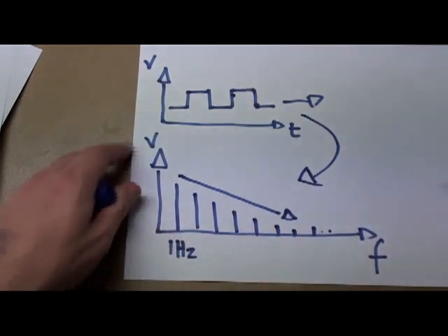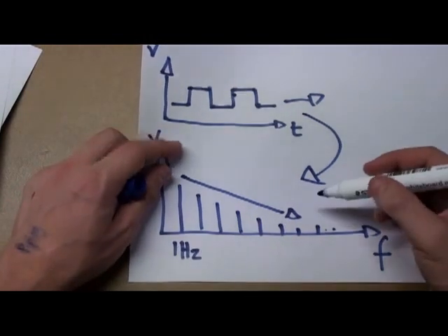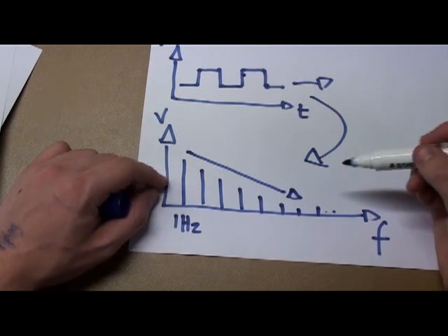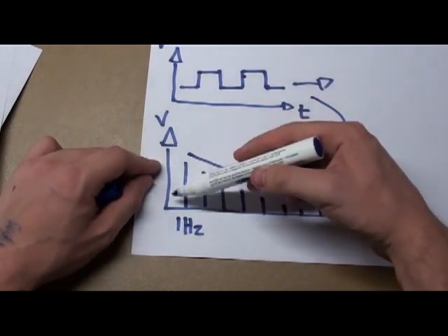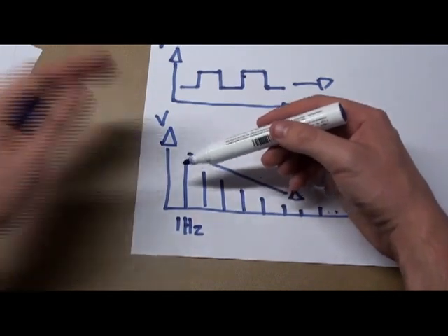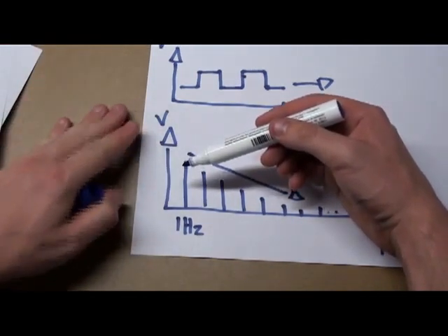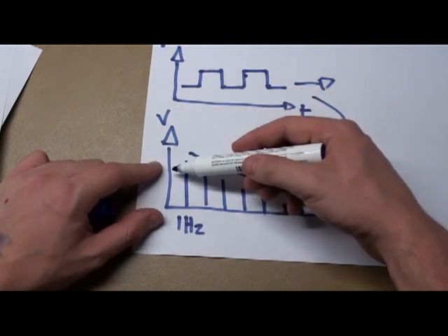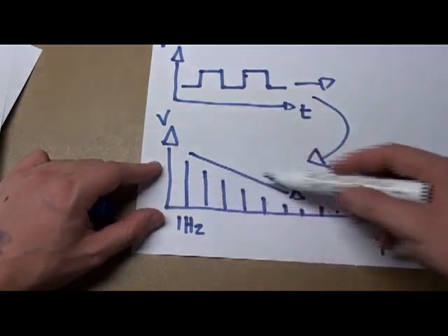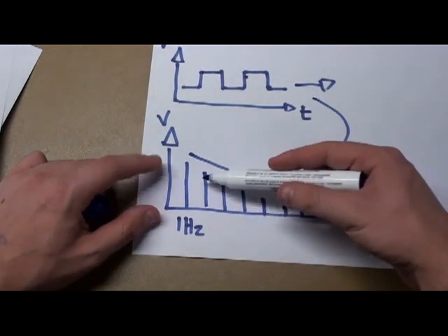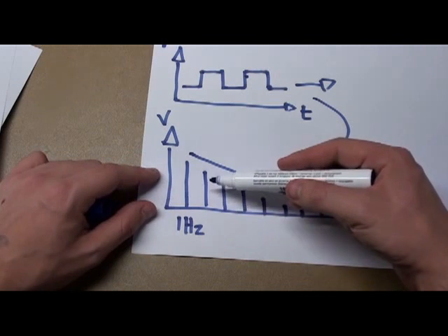There's a bunch of maths where you can put any mathematical function in and you'll get the frequency version. Now this is important to us because our signal from the strain gauge is very slow. It's not going to change very fast at all because it depends on how hard you're pushing down on the piece of metal. So we're not really interested in all these sine waves up here. They're just useless information, and if we have them, they'll get in the way.